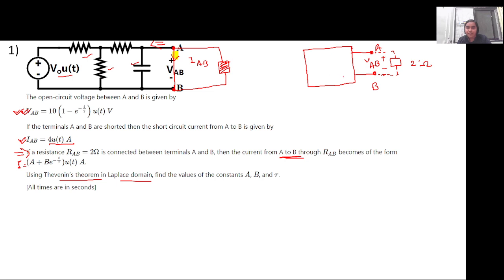So you don't really know. In case of Thevenin's theorem, what does it state? That whatever be, if this is a linear network in which there may be other circuit elements, for example, here there is a voltage source, there is a resistance, there is a parallel combination and series combination of resistance and a capacitance. Whatever be it, if this is a linear network, then it can be replaced by an equivalent voltage, which is known as the Thevenin's voltage, in series with a resistance which is the Thevenin's equivalent resistance. This resistance is actually the resistance of the circuit as seen from this terminal AB, and in which the sources, for example in this case this is the voltage source, are replaced by their internal resistance. So voltage source will be short circuited and current source will be open circuited.